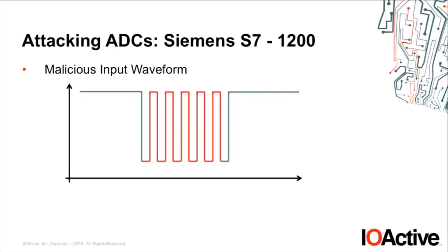So why does this work? It works because of the way programmers, where I also worked a few years ago with this type of systems, usually do it: you read a value and then you start doing something else, right? You are not continuously monitoring the system. You say, okay, I'm going to monitor this just once per second or every 2 seconds. You probably read during 100 milliseconds, read a few values, take the average to remove some outliers that can cause some quantification problems, and everything is fine, and then you go to sleep. But following this approach, of course, while you are sleeping, the system can be changing.